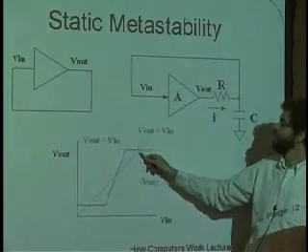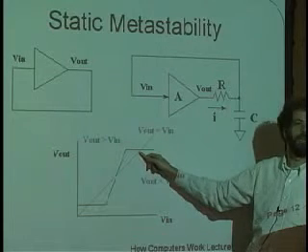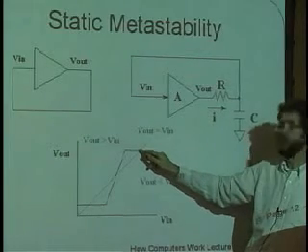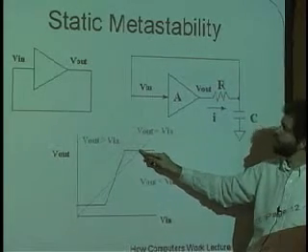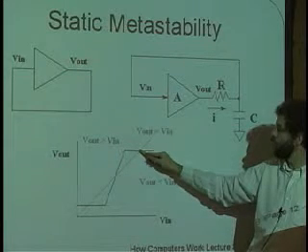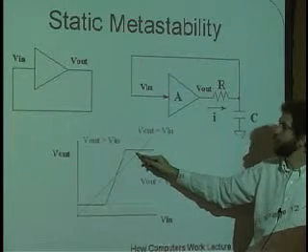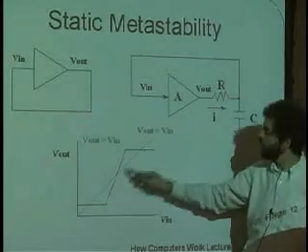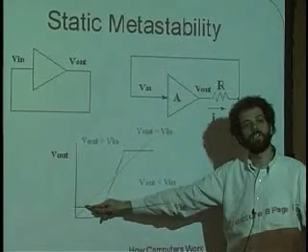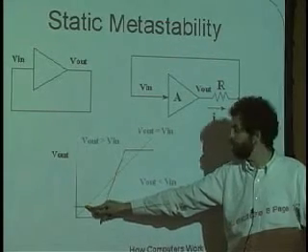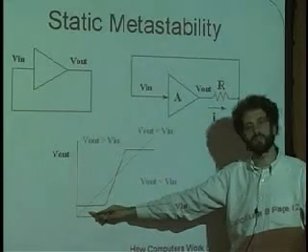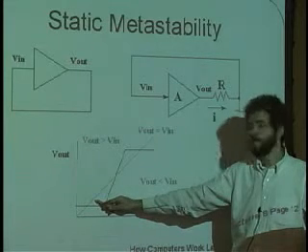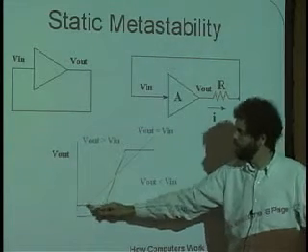This place over here is what's called the stable high state. In other words, this circuit is capable of latching a high value right here. And if, for whatever reason, because of leakage or noise or whatever, the voltage begins to decrease a little bit, the amplification of the buffer will push it back up. In a similar way, this state down here, which is called the low state, the stable low state, works the same way. It holds on to a low voltage value, and if there's a little bit of drift in that value because of noise or some leakage, it'll push it back down again.